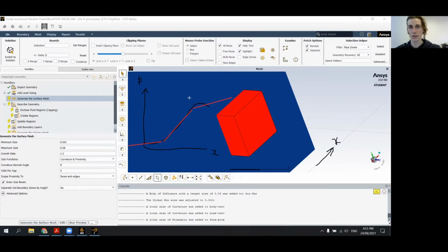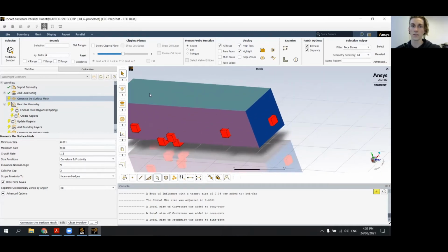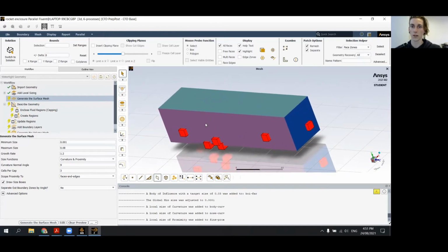Now, in this case, you can see that it's probably not ideal up here because our pressure is changing quite dramatically in a small space. However, for this region here, where the pressure is not really changing over 50 millimeters, it is a pretty accurate representation. So maybe for this area where it's curving, we might want to try smaller elements, something like elements this size, and that'll fit to that curve quite nicely. So that's a crash course in how to select your mesh size. And I think this is going to be more than adequate.